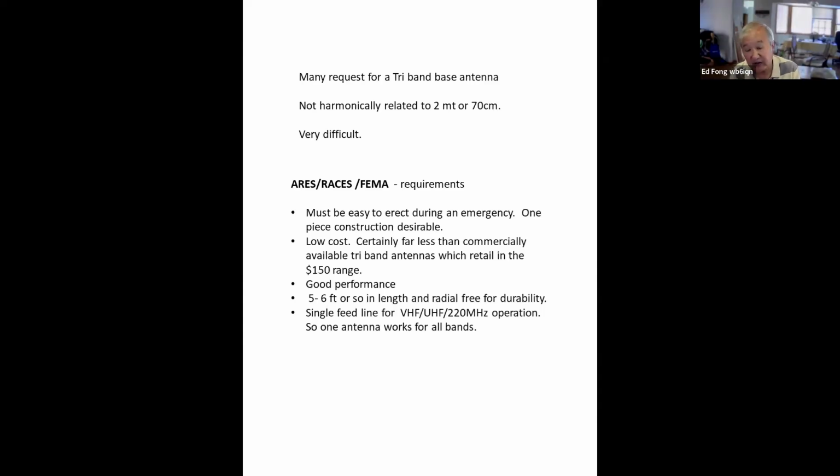An emergency van for FEMA's got a bunch of stuff. Some hams just think, isn't it all communications? No, it's disaster recovery in their vans. The radio is part of it. It's actually a small part of it. But they do cover 2 meters, 220, 440. The 220 is mainly used for packet. If you guys are involved in FEMA, you'll know the standard there. They use packet on 220 because it doesn't interfere with VHF, UHF voice.